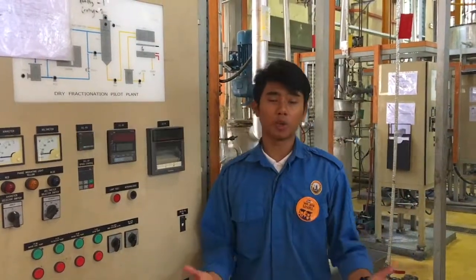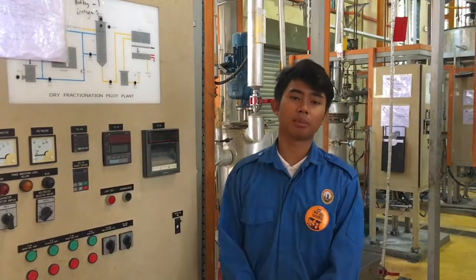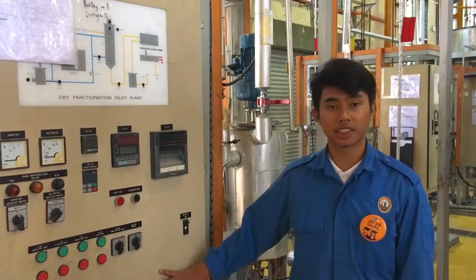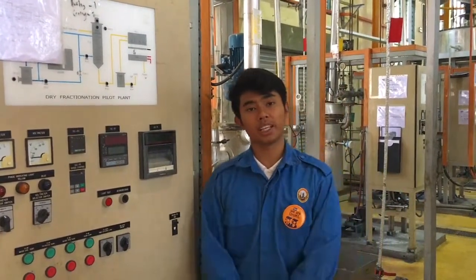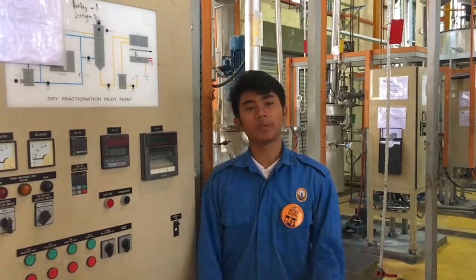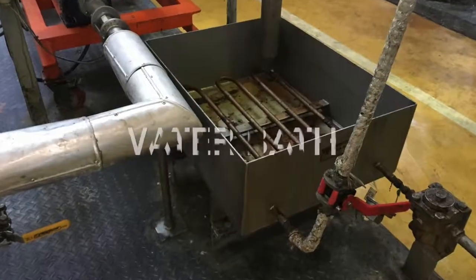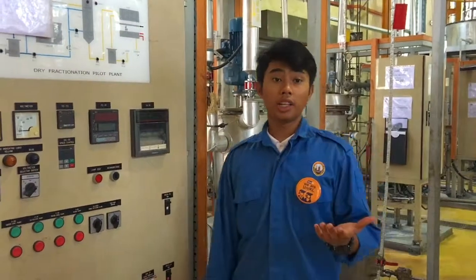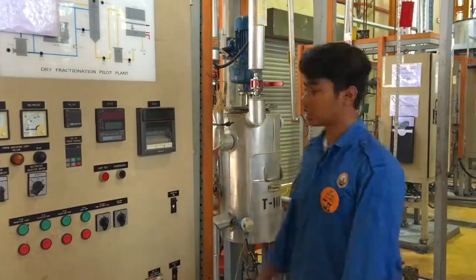First, RBDPO must pass quality specification before it is fed to the heat exchanger. Then, after it is fed in the heat exchanger, RBDPO is heated using a water bath at 75 degrees Celsius. Then, the oil is kept homogenized at 70 degrees Celsius in homogenizers before the start of the crystallization process. Oil is then pumped to the crystallizer.